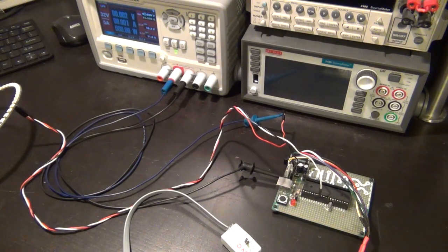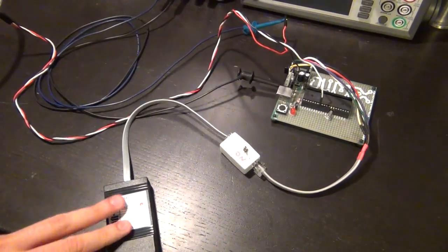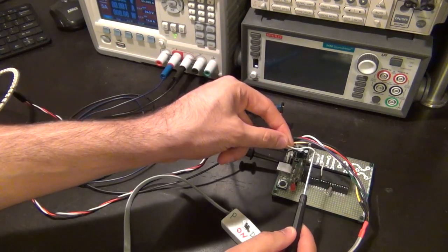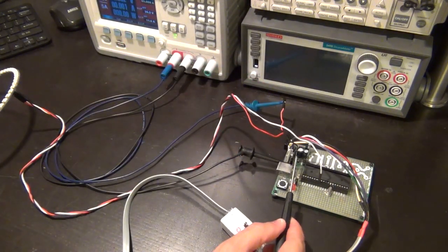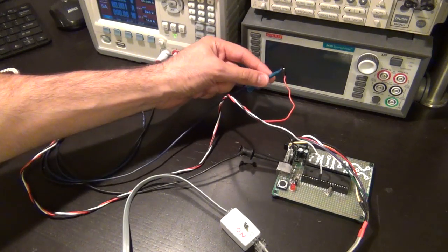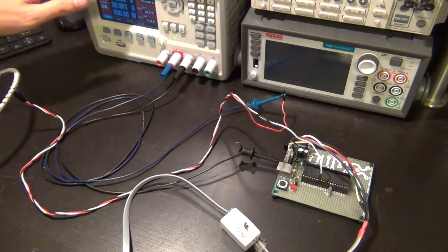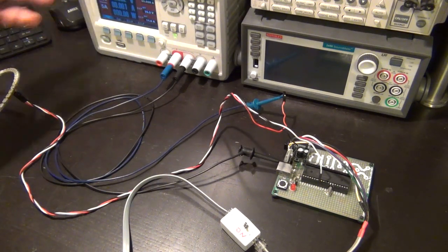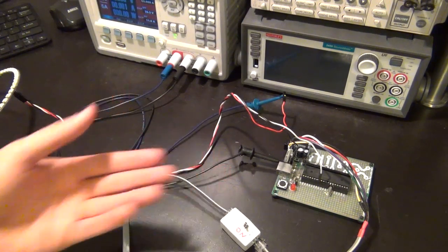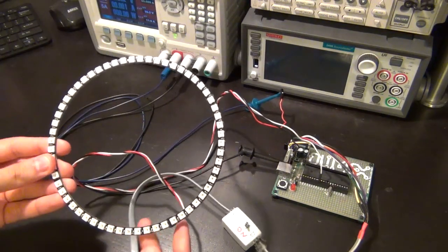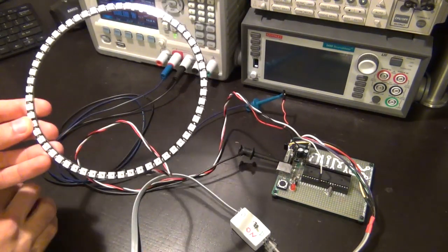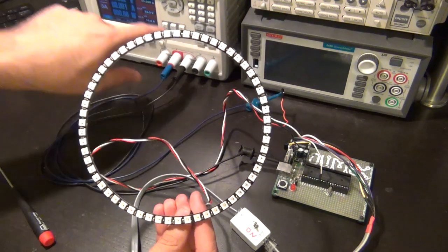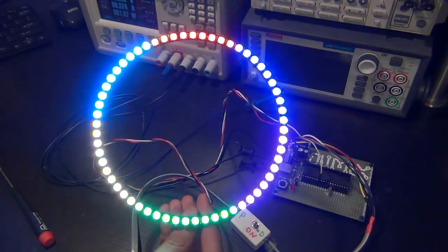So here's our final setup, really straightforward. I haven't done anything. Here's the programmer connected with the ICD to the evaluation board. Now I'm connecting the data input of the NeoPixel to pin E0. I'm grounding the other one, and I'm providing power externally through my Rigol DP116A power supply directly to it. Everything is programmed, the chip is running, and this thing is turned off because the power supply is turned off. So let me go ahead and turn the power supply on, and we should see the rotating ring of colors. Let's see. There it is.